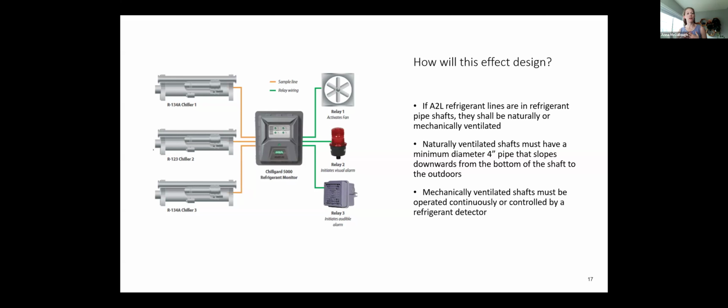You can also, if you do not have the capability to provide that 4-inch pipe to the outdoors, have the option to provide a mechanically ventilated shaft. And that mechanical ventilation must be operated continuously or controlled by a refrigerant detector.